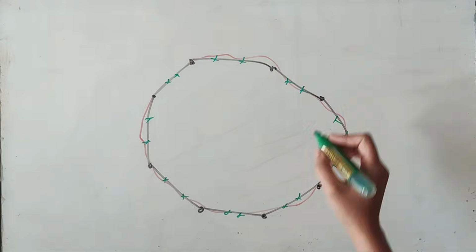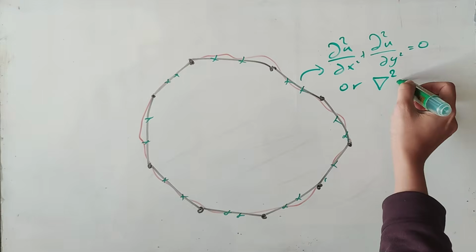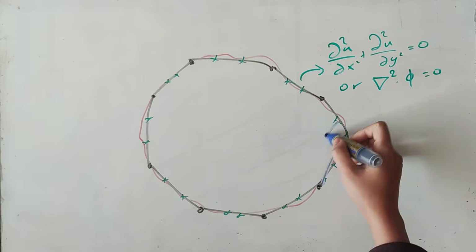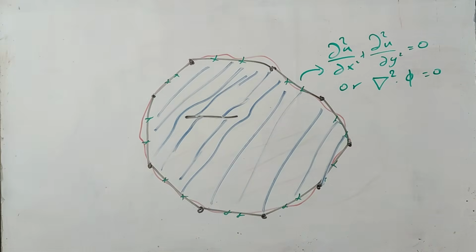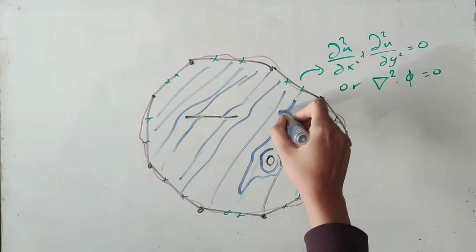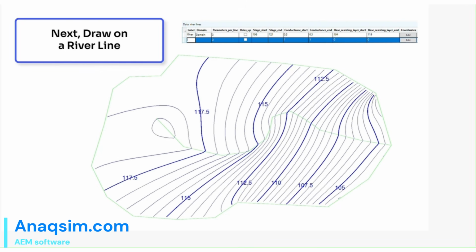In AEM, the governing equation is Laplace's equation. Because analytical solutions to this equation are known, AEM builds the global solution by superimposing analytical elements, each representing a physical feature such as a boundary, a source, a sink, or heterogeneity. This is a cool software that uses the AEM called Anaxim. You can see how adding the elements changes the flow field almost instantly.